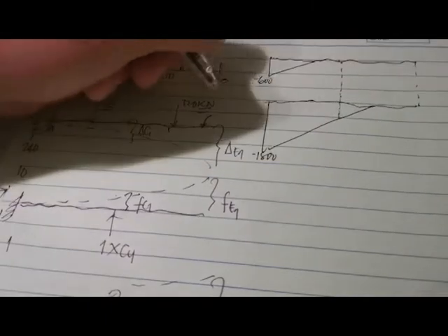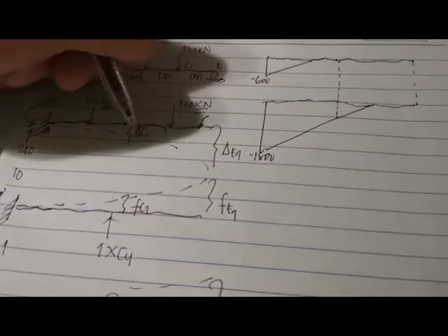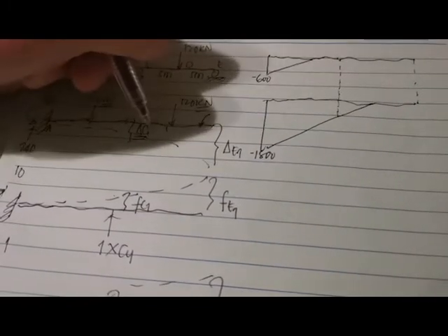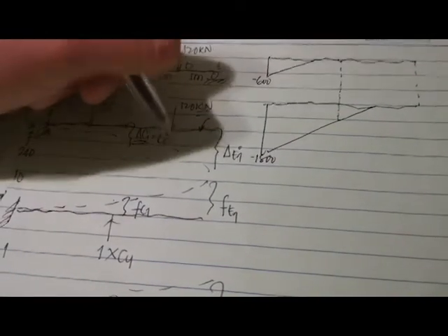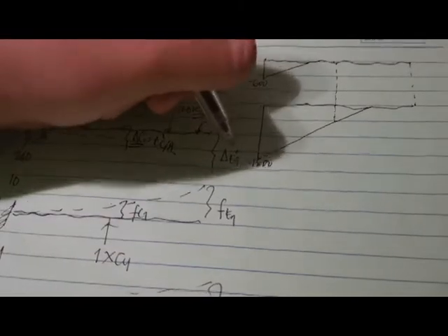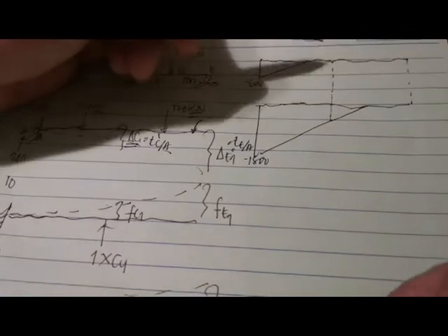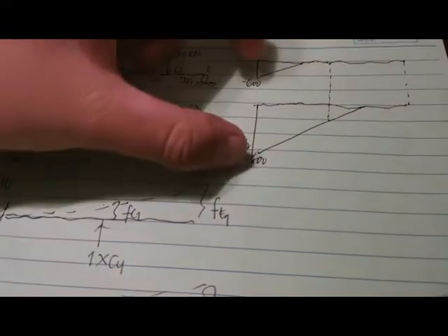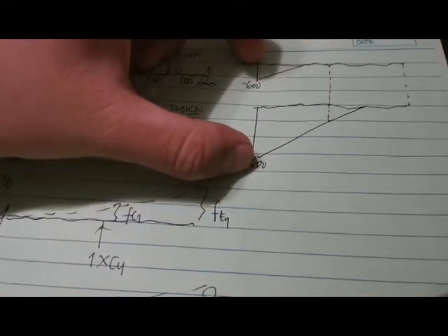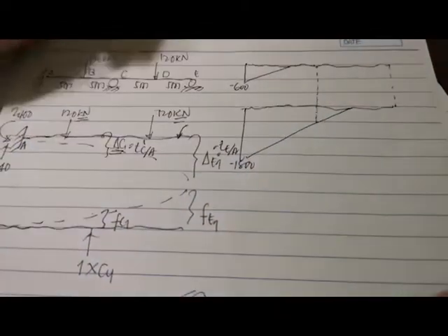Because the horizontal line here can be assumed already as your tangent from point A. And then I can conclude that your delta C1 and delta E1 are equal to the tangential deviation of C with respect to A, then tangential deviation of E with respect to A. And the tangential deviations are equal to the first moment of area of the moment diagram from A to the point we're going to consider.